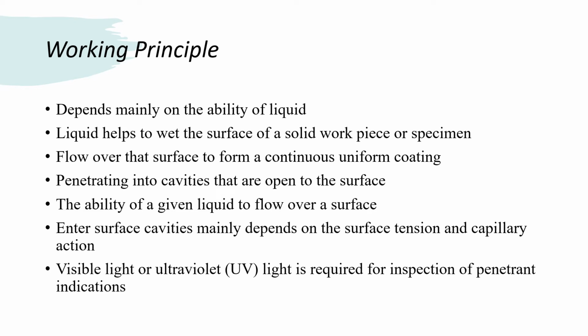Visible light or ultraviolet light is required. Visible light and ultraviolet light is required for inspection of penetrant indication. Initially, the only detection method was the unaided observation by the eye of the inspector under the visible light.